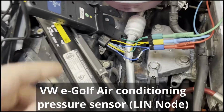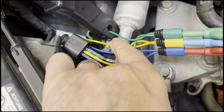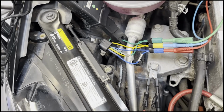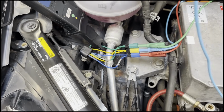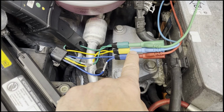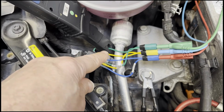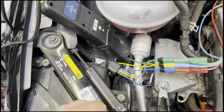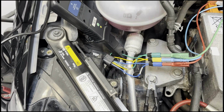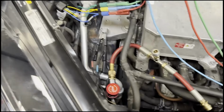We're going to look at identifying this sensor. So there it is, amongst all my breakout leads, the air conditioning pressure switch, which is a LIN node, a LIN module. Got breakout leads on there. We've got the ground path, we've got the LIN signal, and then we've got the power supply to the sensor. Note also around the ground path that we've also got a current clamp, as we know that this device will switch and pull down the voltage to near zero, so we can use that to our advantage.